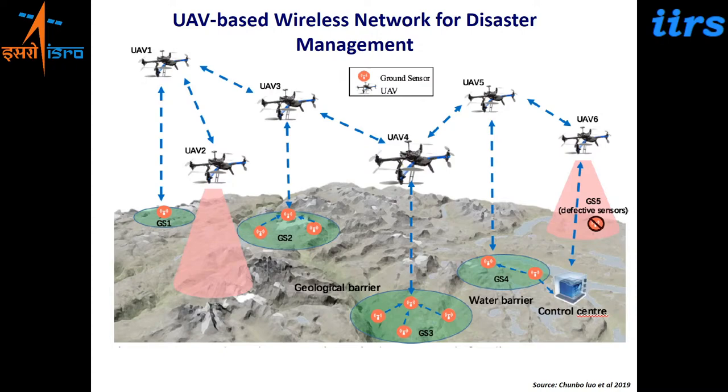There are several mechanisms by which one can use UAVs with wireless sensor networks. One is UAVs can be regarded as mobile base stations or data mules in the sky to provide the communication between the wireless sensor network and the decision-making center. The second scenario could be that a UAV can be integrated into a wireless sensor-based early warning system when a certain node or a part of the network architecture is completely failing. So a UAV could be deployed as a relay node in the entire network to deliver data among the remote wireless sensor network nodes which are placed there.